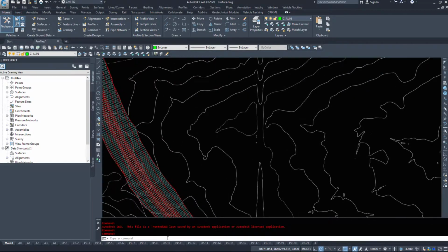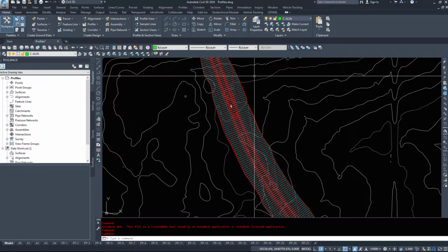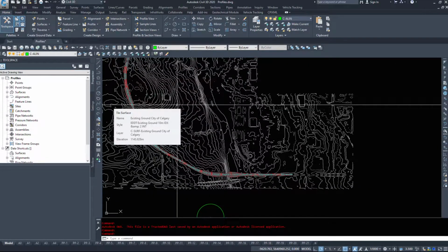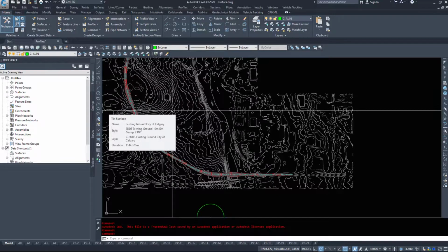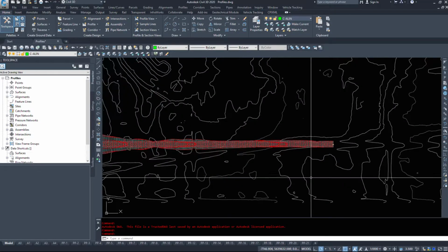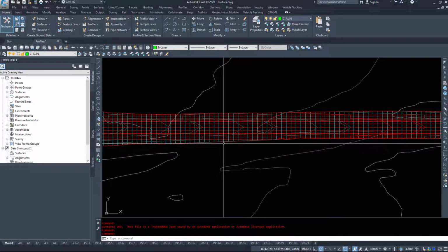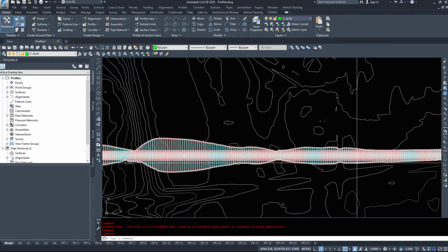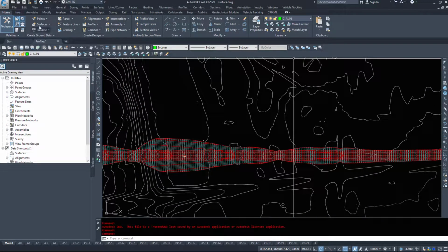So we'll be creating a whole bunch of cross sections down the length of this highway in order to show what, say, every 50 meters looks like in a cross section. And these do get sent out to the contractor so they can accurately figure out where to put dirt and lay things out and whatnot. So we have all the bits and pieces now, we can make our sections.